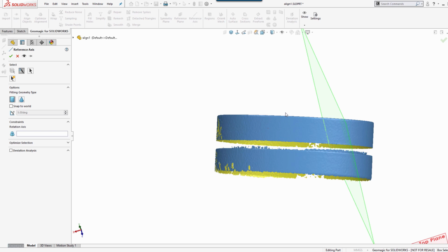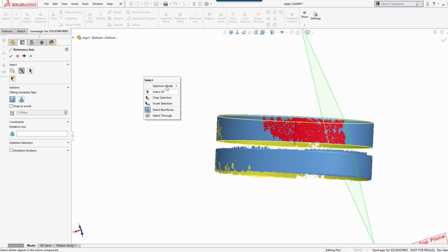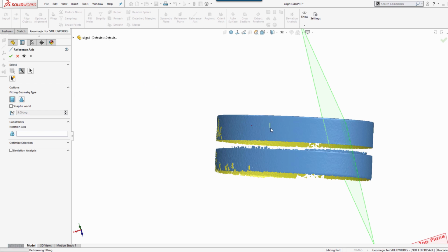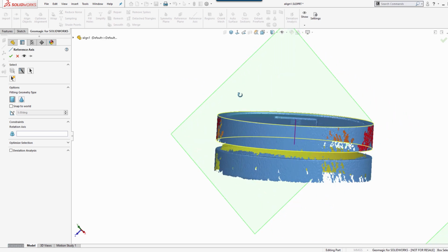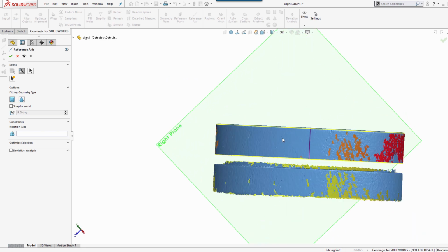So on this, basically what you're doing is we've got this little Smart Select tool, and I'm just dragging a little box window. I want to bail out there. Let me right click and clear that out. So again, I'm just drawing a window, and as I drag, the further up I drag, the more of that data it selects. I'm still holding my mouse down, just left dragging basically like a selection box. And if I keep going, it goes all the way to the top and everything. So when you're not doing a webinar, it's a lot smoother. Okay, so that grabs a lot of data. If you want to grab some of the other side, you just turn back, hold your shift, and do basically the same process again.